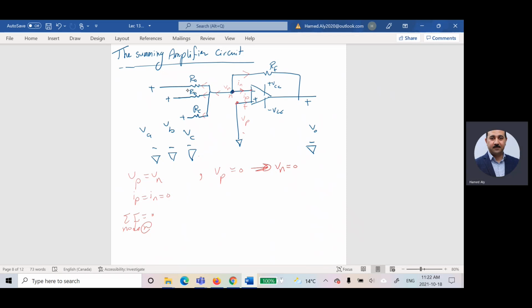So the current in this guy is Vn minus Va over Ra, plus the current in this guy is Vn minus Vb divided by Rb, right?